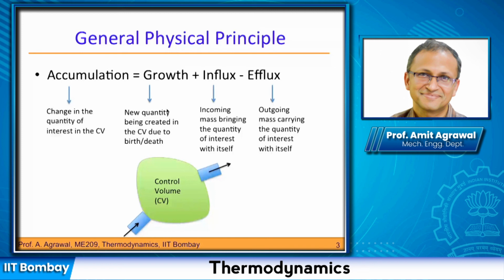So basically, what we are saying is, for a given pressure and a given temperature, what is the actual volume that the gas is occupying, divided by the volume as per the ideal gas law that it would have occupied. The ratio of these two is my compressibility factor. If we are given the volume of the container, then won't the actual volume just be that value? Yes, that is right.